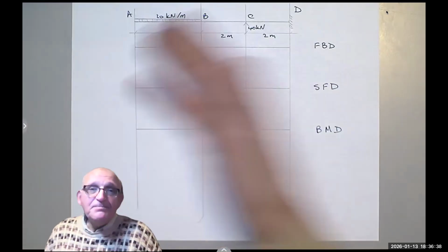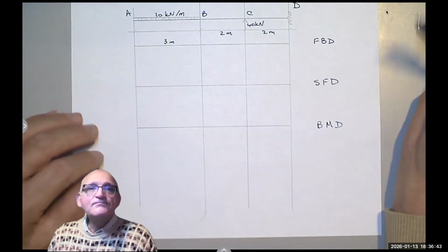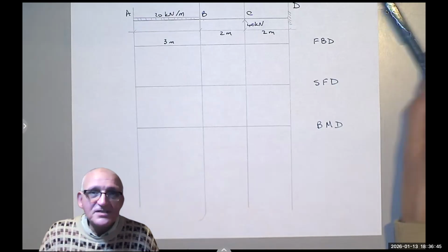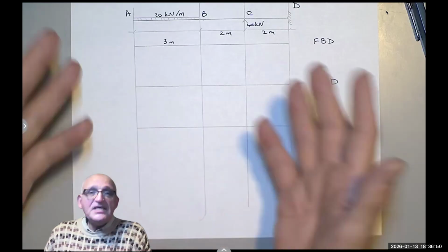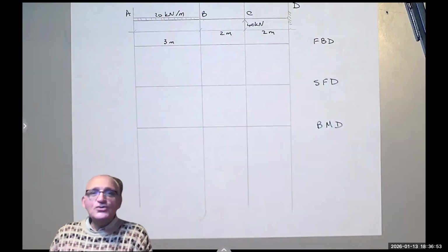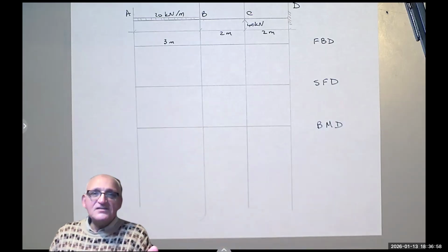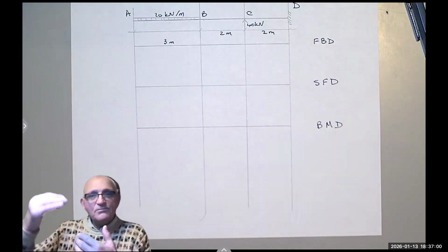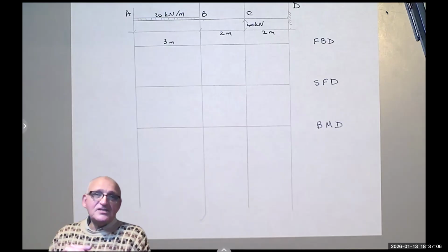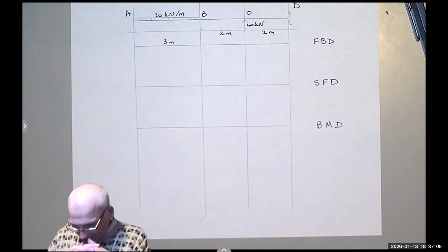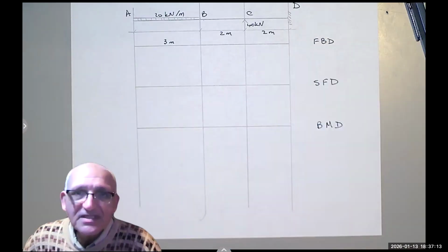So here is my beam. It's a cantilever beam because there is a fixed support on the right, so you don't need any more supports. If you add a support, your beam would be statically indeterminate, meaning using statics alone, you won't be able to find the reactions at the support, and you will need to look at the deformations and use more advanced material that you usually cover in a strength of materials course. So here we will assume that we have statically determinate beams, and that's what we are going to do.